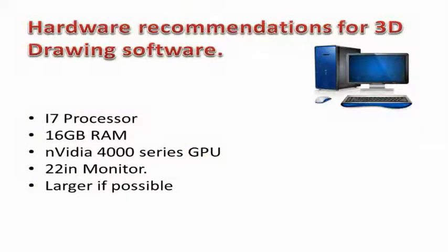So what I would recommend, if you are investing, to stop those crashes: we found, because we were using basically a normal computer box, for want of a better word, with an upgraded graphics card, I would suggest as a minimum you go for 16 gigabytes of RAM, a really good NVIDIA graphics card, and a large monitor, and that will stop most of the crashes, because we did experience a lot of crashes by using hardware which probably wasn't up to the size of the models we ended up working with.